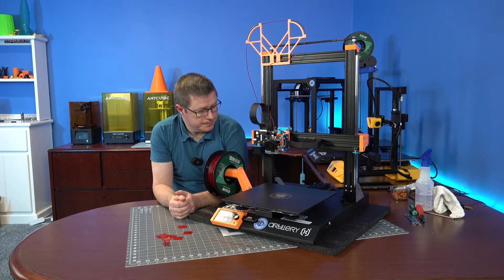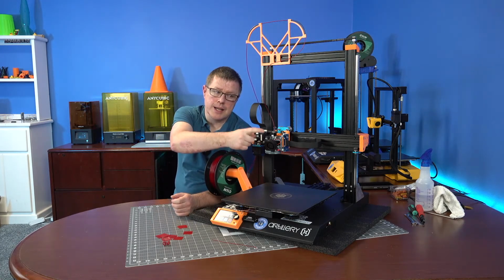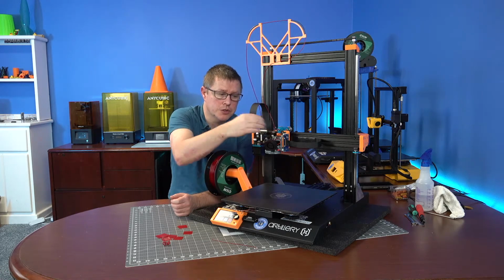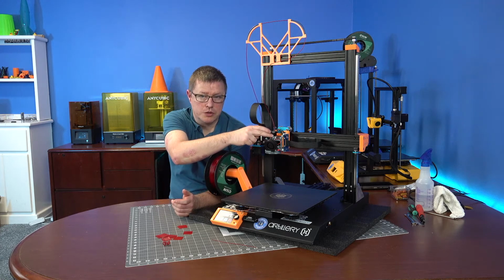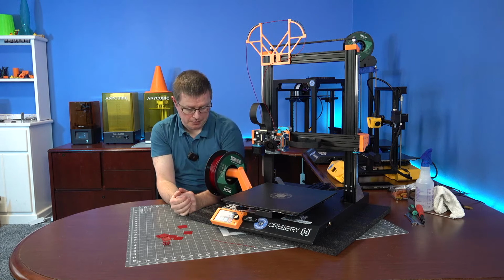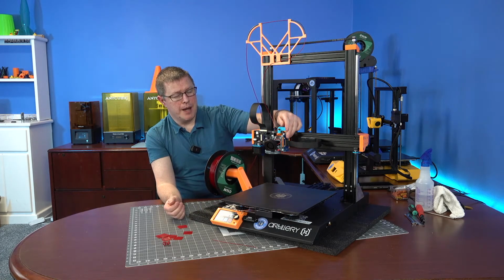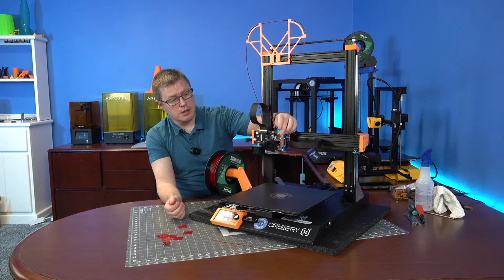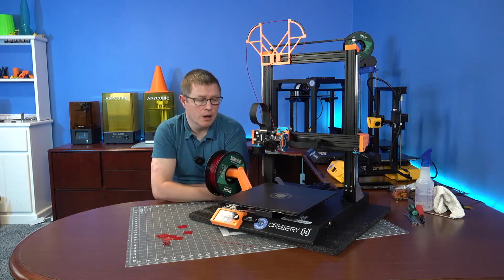Yeah. And eventually I gotta make a fan shroud that works for the Hemera XS setup because everything's just closer. I mean, you could use this, you just only have one screw hole to use, so it would probably eventually move on you, so I gotta do some finagling in the model. Plus, I would imagine you'd want to use a thicker spacer to move the breakout board out and away just so it's not getting in the way of your fan on that.